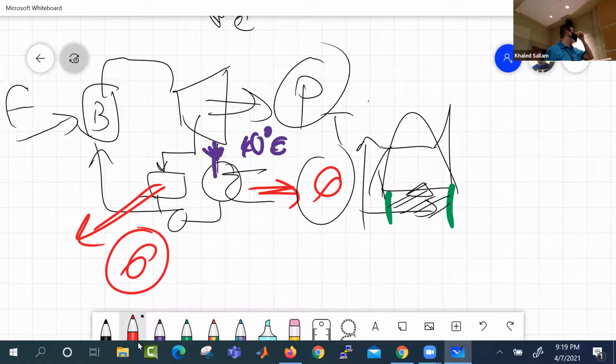Okay, so what I'm trying to say is that the combined heat and power cycle doesn't always have to extract heat at the bottom. It could extract heat in the middle of the cycle. Of course, that heat in the middle is more valuable than the heat at the bottom, because the heat at the bottom is totally waste for us. We just have to reject it. But when we extract from the middle, it's like this place, like he's extracting heat over here. This is bad for us as a cycle because it's cutting from our work. I mean, you are losing steam that was supposed to go to the turbine, right?